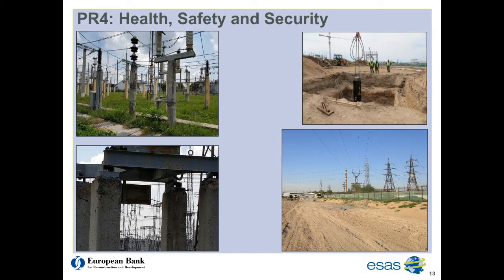Firstly, there is no documented lifting plan. Lifting operations are not supervised by a trained, competent signaller or banksman, which is also known as a spotter. The client does not provide constant supervision of lifting operations by a competent electrician familiar with the site. This is critical given the presence of live electrical systems and a contractor who is unfamiliar with the facility.